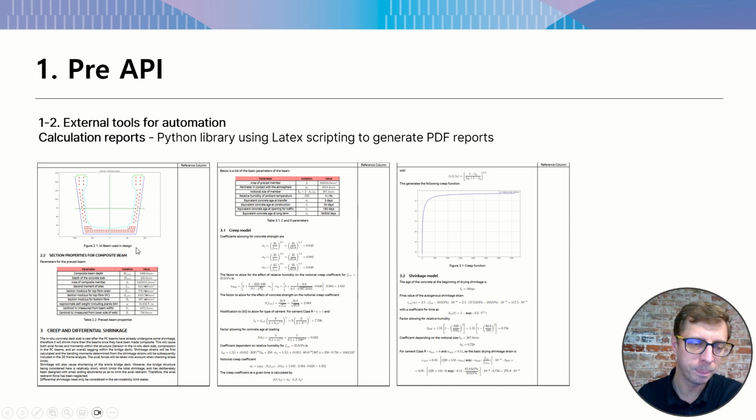Here's a W-beam used. The different colors signify internal or external surfaces within the beam. These are all the tendons within the beam. All of this is automated in the Python script. All of this is generated. The idea being to make it as simple as possible and to separate creating all of your elements, your calculation reports, from the formatting that is done within the calculation report.